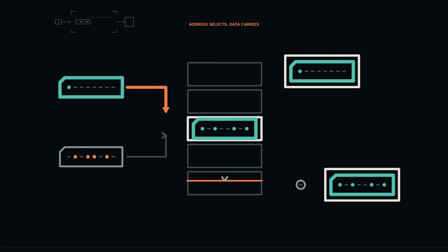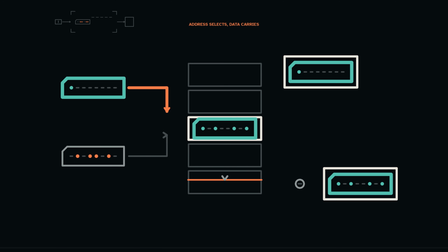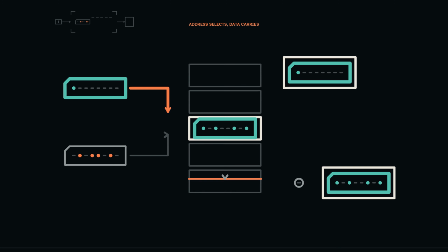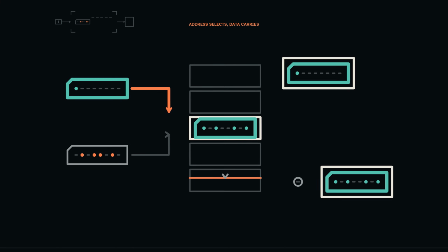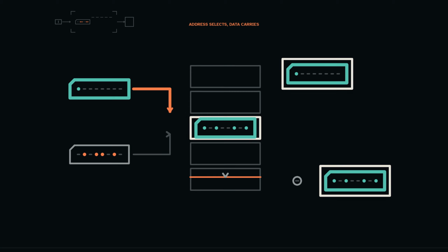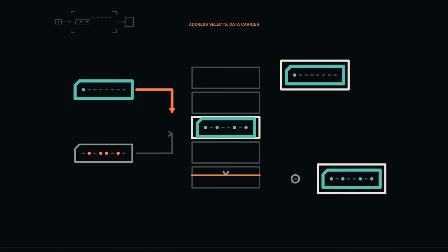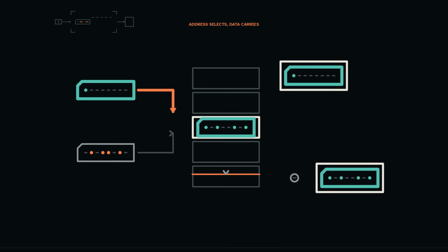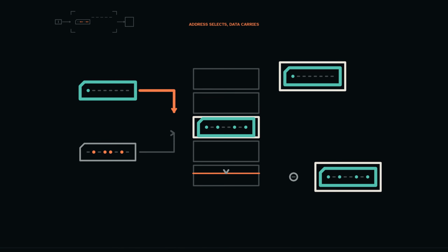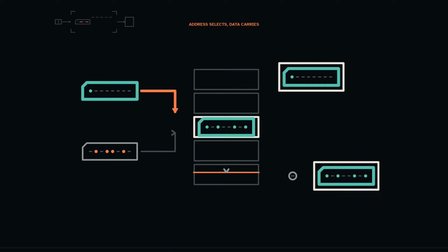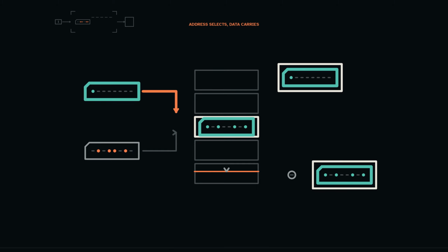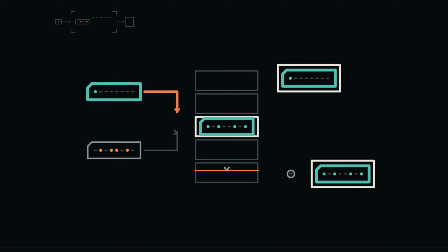Before the edge, MAR is unchanged while the bus presents the new address. At the edge, MAR captures 80. The decoder now selects location 80, but the stored byte has not changed. An address answers which one. It does not perform the write. If the data source were wrong at this moment, no memory cell should yet be altered. This separate address phase makes the destination stable before any commit is authorized.